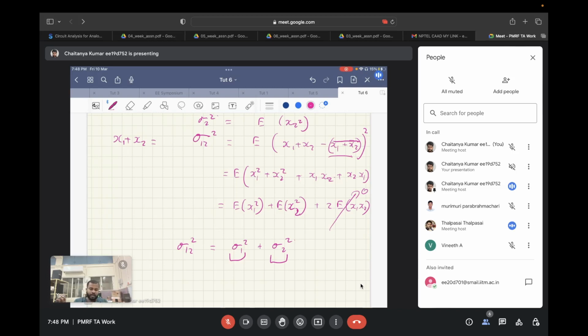So it's non-linear. Now if you put a complete voltage swing at the input of that transconductor, at the output the current will be non-linear. It won't be a linear function of the input voltage. So there you will get non-linearity. But in active RC networks, there is a virtual ground. The op amp is made of these transistors, but since at the input of the op amp there is a virtual ground, that node won't swing much.